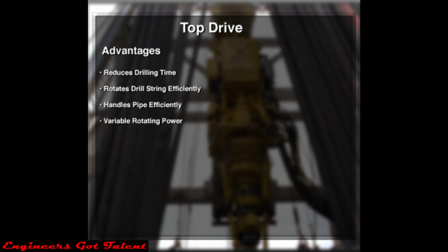A top drive system provides more variable rotating power than a rotary table. It allows drill string rotation and circulation at any point in the hole when tripping in, drilling, or tripping out. These features help prevent hole problems. It provides rapid response to well kicks during tripping or running casing.